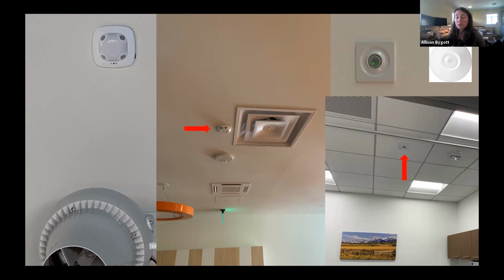When you're making a Revit model with your design, you can turn on the work set for HVAC and you can turn on the work set for lighting control. And it's so helpful if these sensors get moved 6 feet away. If we just assume that the electrical contractor is going to take care of that during install because we put a note on the shop drawings that says, please put them 6 feet apart, it doesn't usually happen. And so everyone waits for me to show up and tell them if the daylight sensors or the occupancy sensors are false triggering or not. Sometimes that's hard for me to tell.